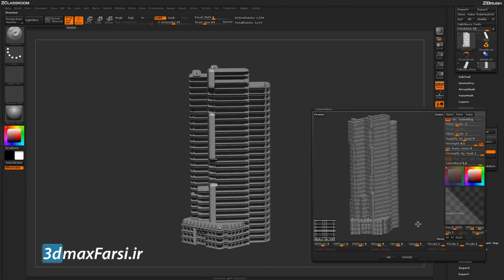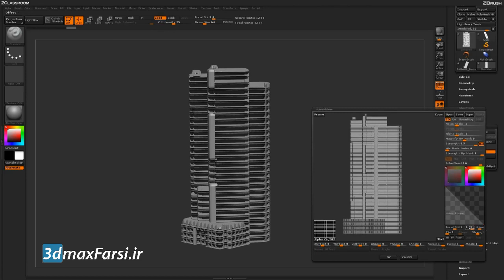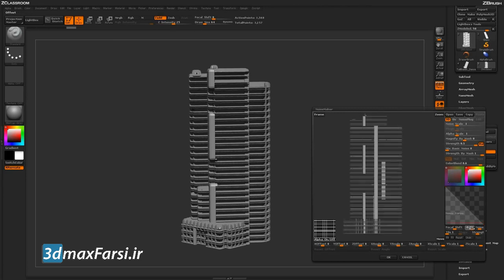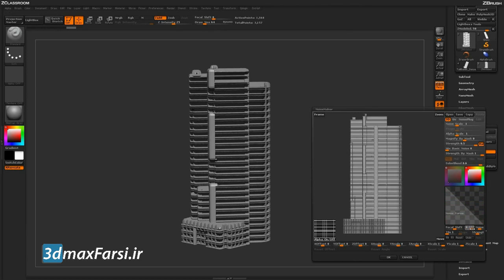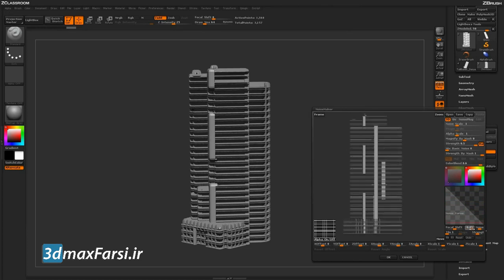The first thing we're going to adjust is this offset slider right here. So if I position my model here to the side and then start adjusting this offset, it's going to start culling or clipping out parts of the mesh corresponding to the alpha gradient values. As you can see here, as I turned it on, instantly all the black values on the alpha that were being applied to the model have now been culled out. And as I slide this slider up or down, it'll start culling or clipping out more of those values. So I can just cull out a certain area, say something in the middle, so maybe about 0.5.